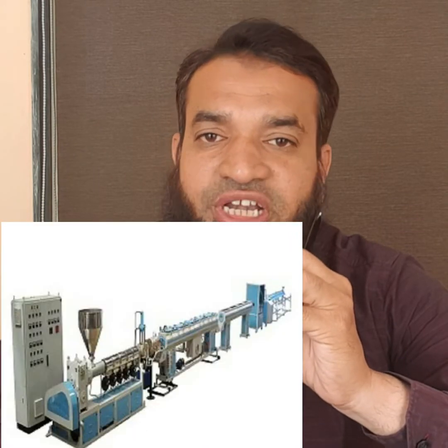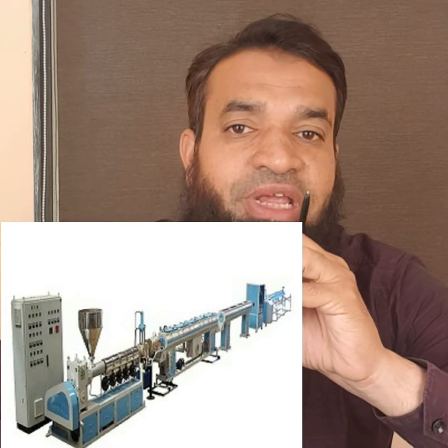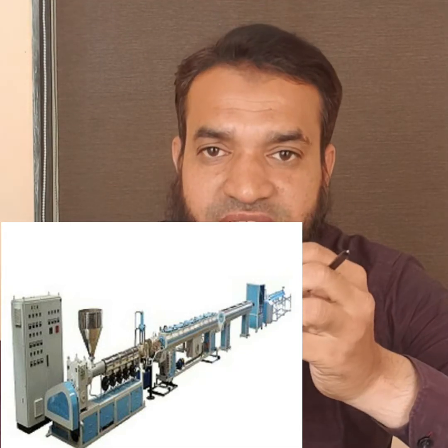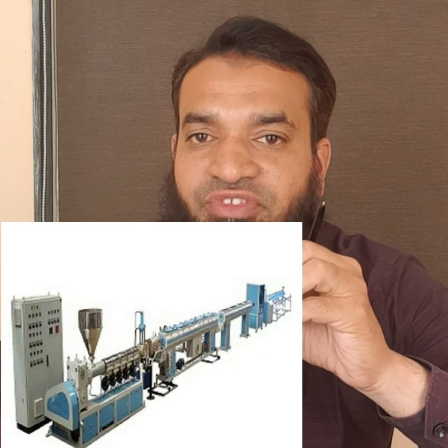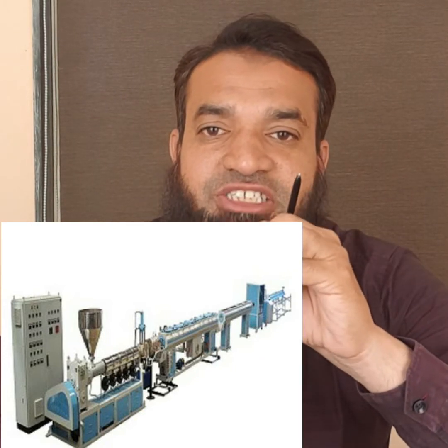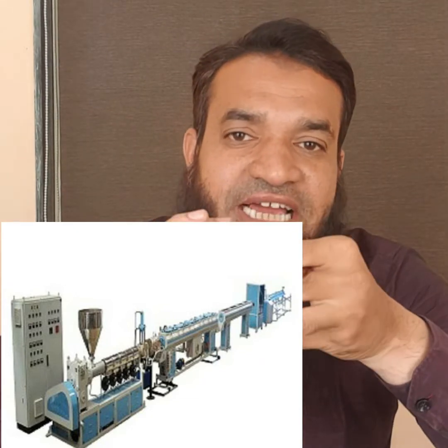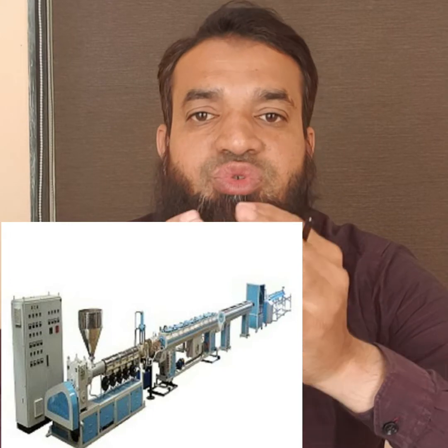In extrusion, similar to injection molding, this also makes use of heat to melt the plastic granules. The difference comes at the final section of the machine. In this case, the melted plastic goes through a pre-designed opening and is then cooled down to solidify.